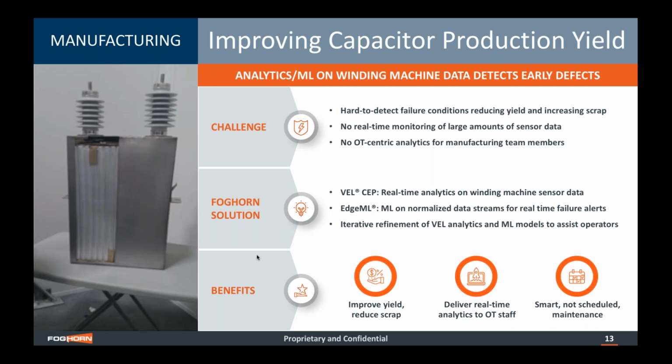And then the second step is to run it through what is called a treat oven, which is to take out all of the moisture from the capacitor, subject it to heat and pressure conditions. And finally, they fill different types of oil into the capacitor and then test it. At this point, their challenge was when they sealed the capacitor and tested, a lot of them were seeing dielectric failures, right? When that becomes a scrap. So this was costing them millions of dollars because there's a lot of scrap.